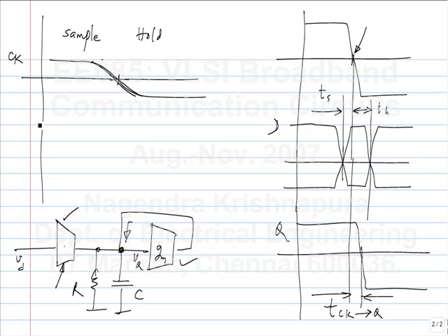Okay. So let's say the input changes from negative to positive just before the clock and then back to negative. That is kind of the worst case for latching. Then the Q was at negative, maybe it reached a small positive value, but here it reaches negative.